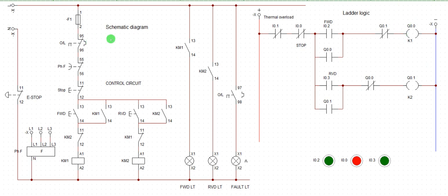All right. So let's relate them here now. Like I told you, this is my output. What I have here is input 1, input 2, input 3, input 4. Only 4 input is what I have in my logic. Then I have 2 output only. Okay. So the connection required here to PLC is 1, 2, 3, 4, 5, 6 only. That is only 6 physical bit connection that I have to do to my PLC.